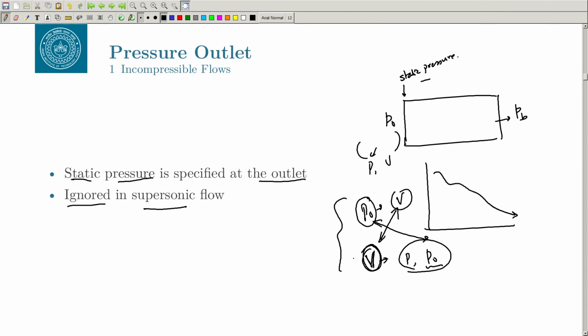Sometimes you want to calculate, let us say, Cp, based on your P at the inlet, the pressure at the inlet. If you have used the boundary condition which is velocity inlet, then you have to take the average pressure at the inlet to get your P, and then you can use this relation: Cp equal to P minus P infinity by half rho U square. So, you know the pressure.